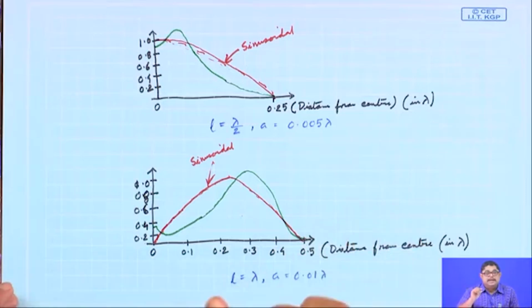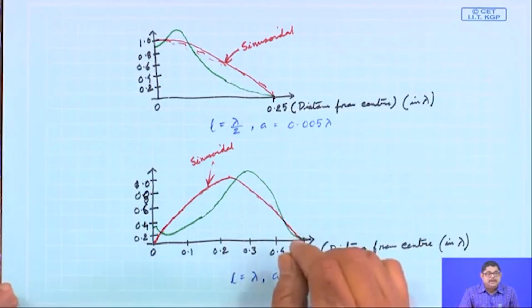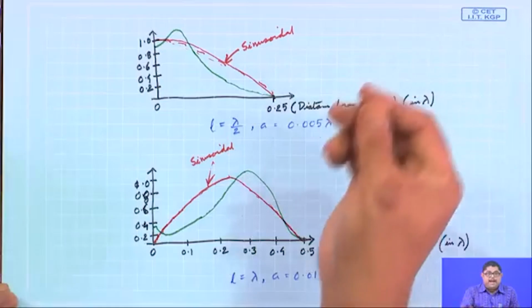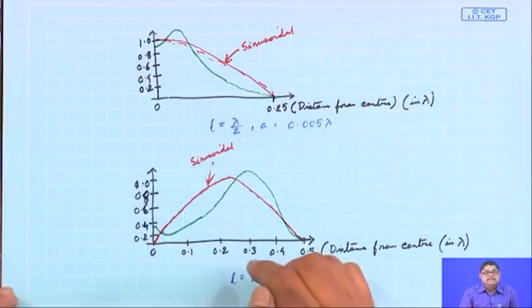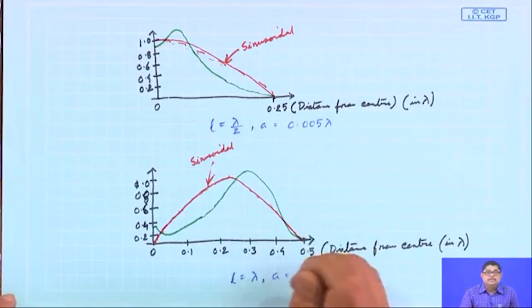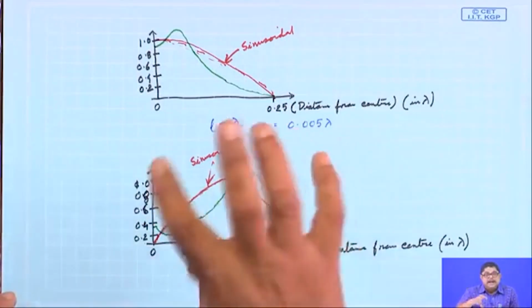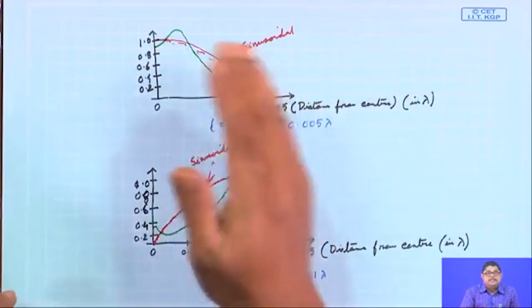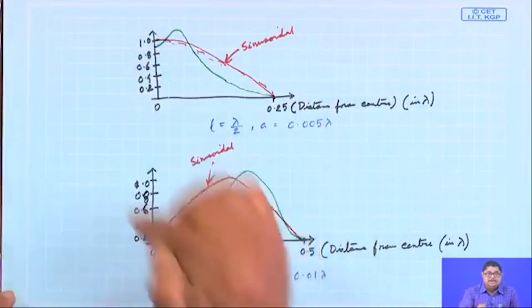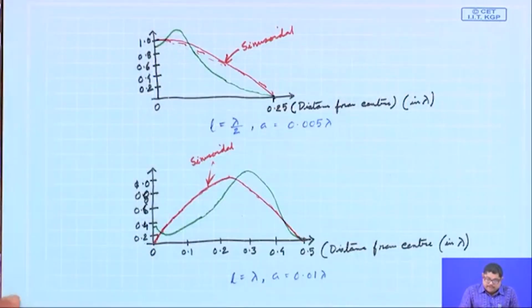The input impedance at the feed point is the applied voltage divided by the current, so if the current is different, the input impedance will be different. Basically, the near field effect is different if we assume a sinusoidal distribution and an actual distribution like this.